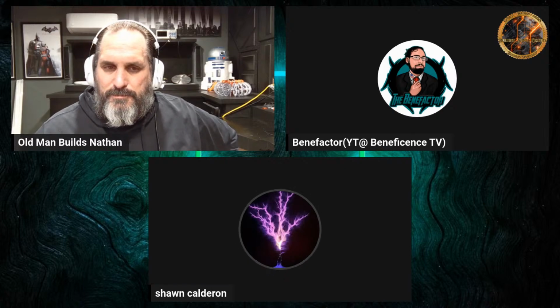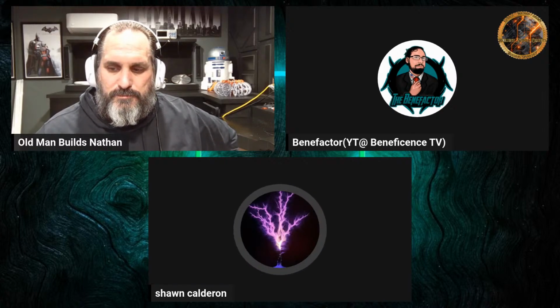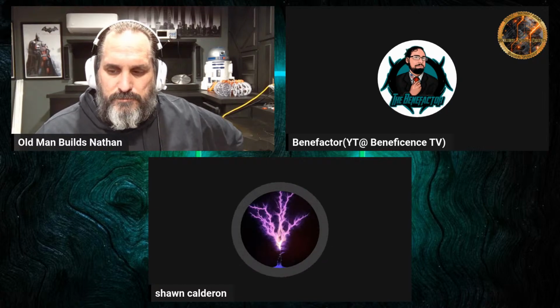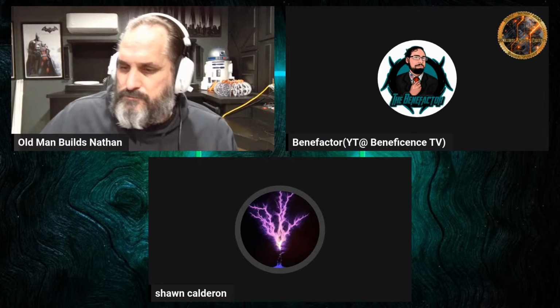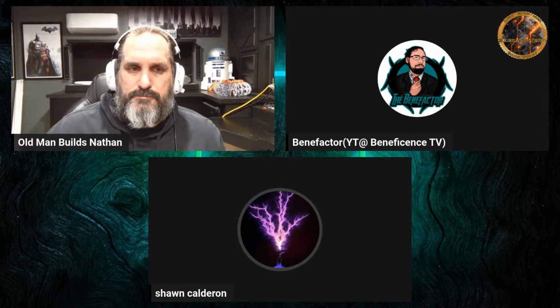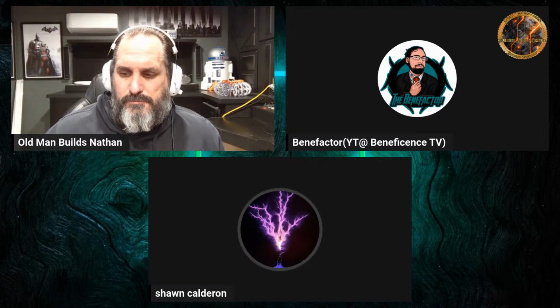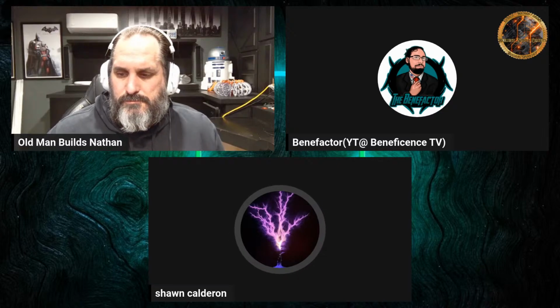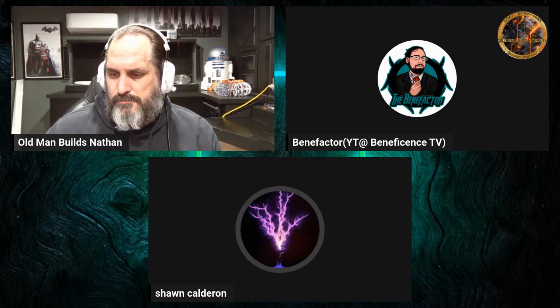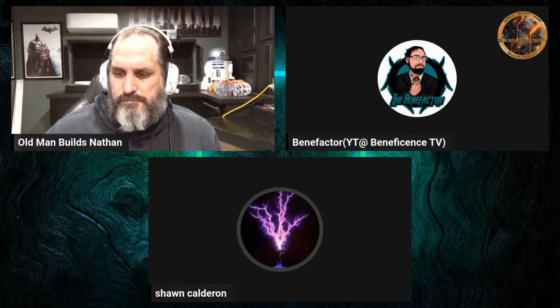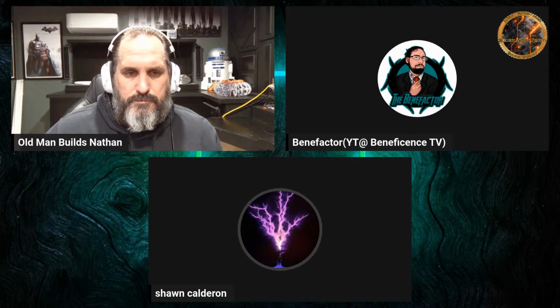So I got something. John Curley's asking in the comments about the Tesla coils I work with. The ZVS Tesla coil resonant frequencies run between about 100 kilohertz to 300 kilohertz. How that's hooked up is between 12 and I would say 50 volts DC as the input to the ZVS circuit, run with about 5 to 8 amps input. The output frequency is between 100 kilohertz and 300 kilohertz, like I mentioned, and the voltage is 600, 700, 800 volts.